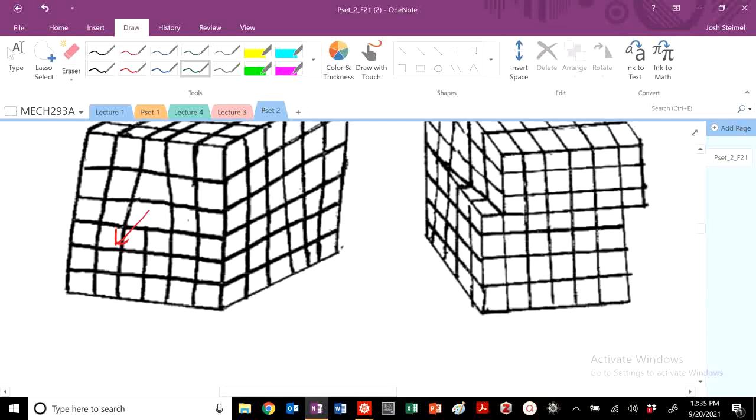I'm going to go again, with the tangent vector coming out of the board like this. Pick my starting point, just right here. I'm going to go 1, 2, 3, 4, repeated four times. So my circuit is not complete. So what is my Burgers vector? Make it black. I'm doing my start to finish. What's the relationship? Perpendicular, edge.